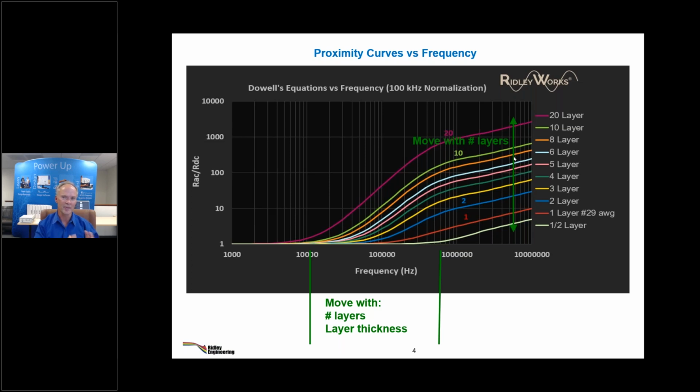That will depend very much on what you're trying to measure. The Ridley box has about the same resolution as the AP in doing these passive circuits. It's just that pulling out these really low resistances in the presence of inductive paths is difficult.